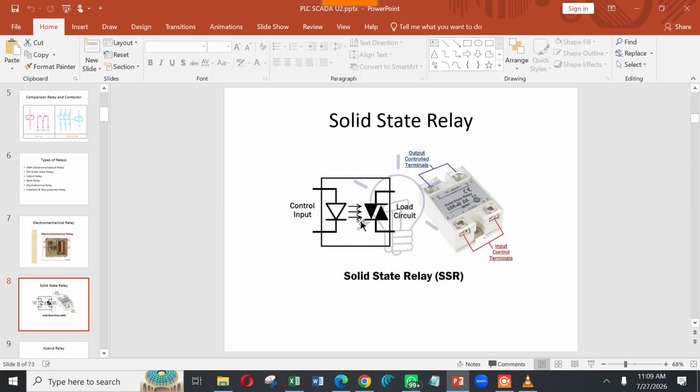In triac, do you know triac? What is the difference between triac and SCR? SCR is used to control DC devices. Triac is used to control AC systems. In the triac, the terminals are terminal 1, terminal 2, then gate. So try to be aware of power electronic devices. They are very important in automation nowadays. Most of the control systems are coming with pure solid state.